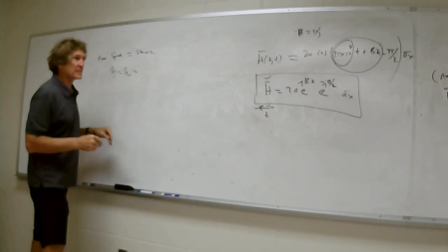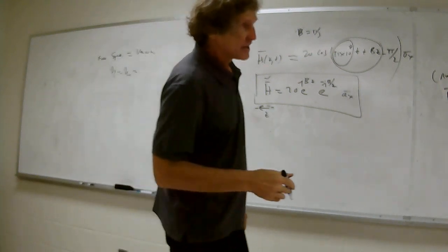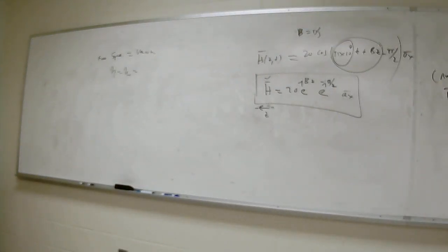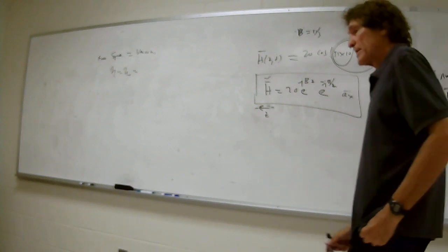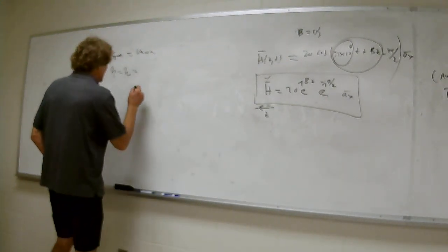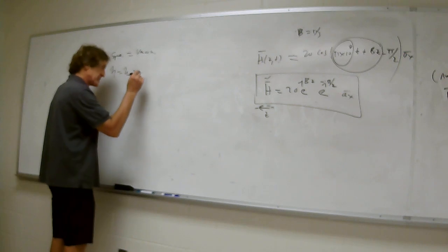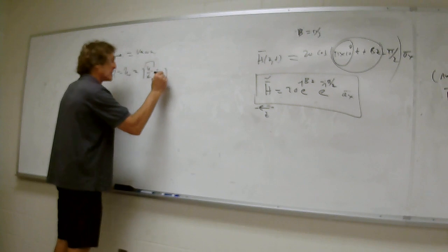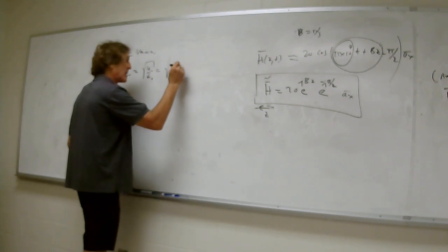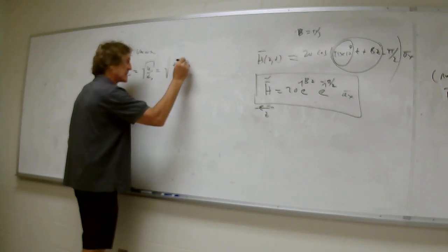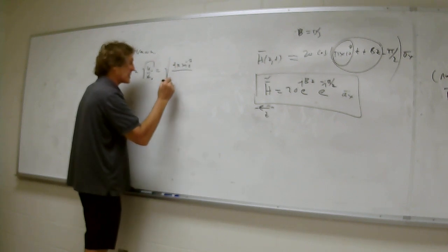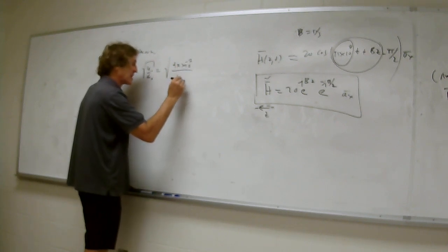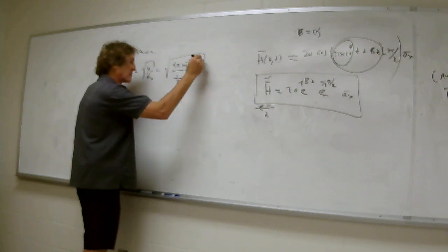And if you think about the definition for intrinsic impedance, look at this. If this is the definition of intrinsic impedance and you're in free space, well, sigma is 0, right? The j and omegas cancel, you get the square root of mu over epsilon. Please write this down, make sure you know it. The intrinsic impedance in free space is equal to the square root of mu over epsilon, or mu naught over epsilon naught. That's the square root of 4 pi times 10 to the minus 7 over, and you can write this as 1 over 36 pi times 10 to the minus 9. Do you all remember that?